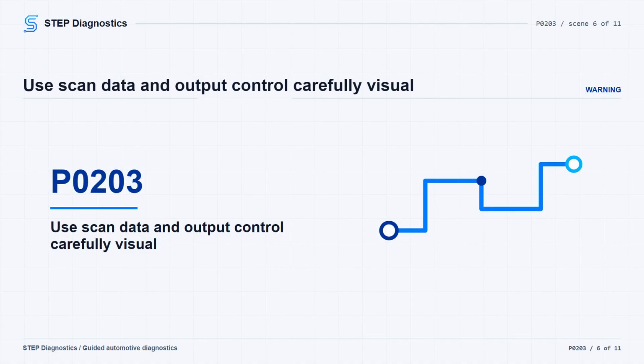Use the scan tool to read PID inputs, output states, and diagnostic states. Data log the PID information so you can watch the fault without tearing the truck apart unnecessarily. Where the scan tool supports it, command outputs and watch how the system responds. Make sure you understand how the system is supposed to work.